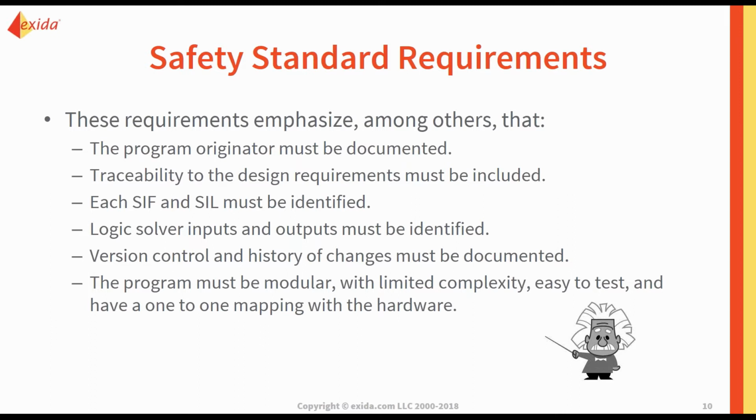You might have to implement more or less redundancy, so that would affect your inputs and outputs. You might have to change your testing strategies. You might have to change your implementation strategy, so trip delays, things like that. And so it's often better to have this traceability to complete your conceptual design before starting your application program. And what I'm going to talk about today would help with that.